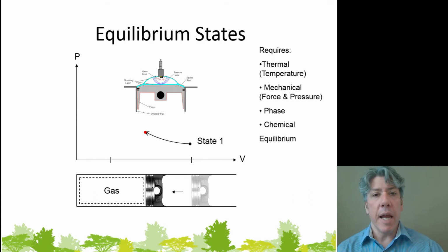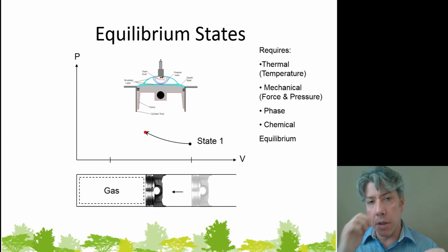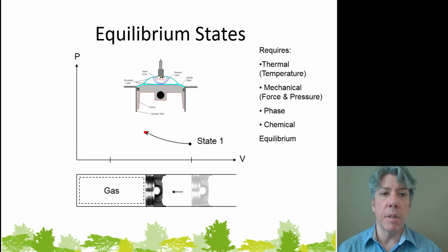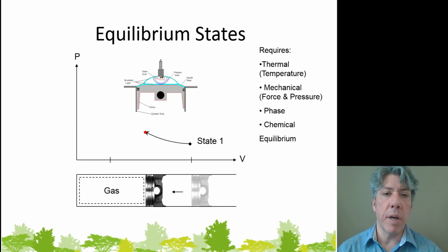Now, if you think about a real piston cylinder device, maybe the one in your car, where the gasoline and air mixture is in the top, the piston has compressed it, and the spark plug lights it up, is that a reasonable estimation, or does the system follow equilibrium? Is it at equilibrium? Well, obviously not, right? When the spark lights up the air-fuel mixture, the properties of the local system around the spark plug are very different than the properties ahead of the pressure wave near the surface of the piston. And that difference means that there are things that are going to happen, right?